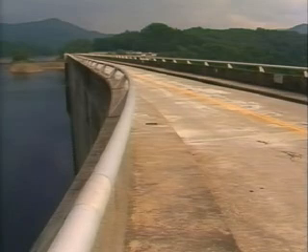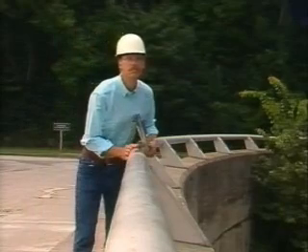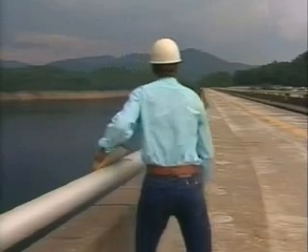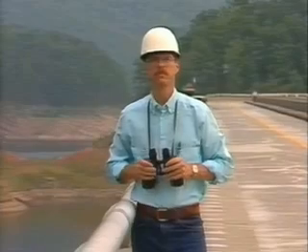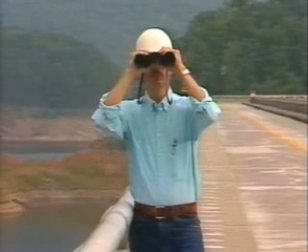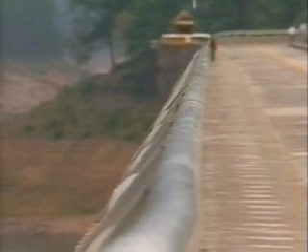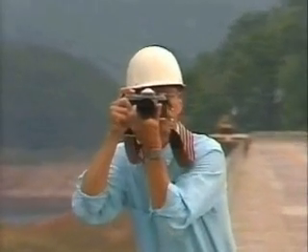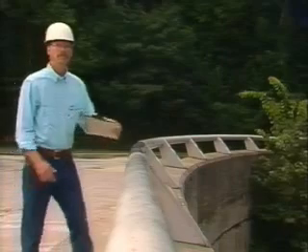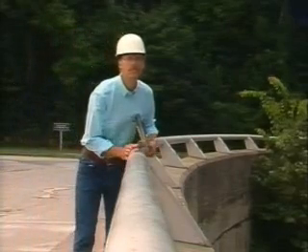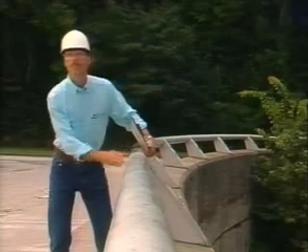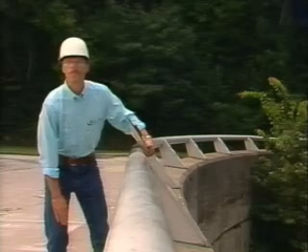There are a number of techniques you can use to detect displacement. One technique when inspecting a dam with a straight axis is to sight along the crest, looking at the structure from several different perspectives. Sighting through binoculars foreshortens distances and often makes irregularities more evident. If binoculars are unavailable, use the telephoto lens on your camera. When sighting, select a linear feature, such as this parapet wall, to serve as a reference line along the crest. Then look along your reference line from several positions.